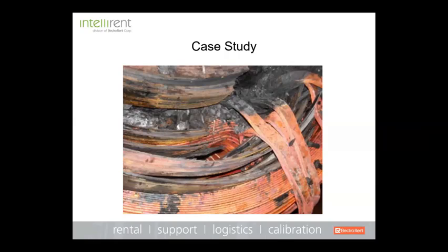If your leakage reactance is not within its limits, or you have experienced through faults according to your monitoring system, I would say take the leakage reactance test one step further and perform an SFRA, because that really is the tell-all as to whether or not you've got some mechanical damage to the transformer.